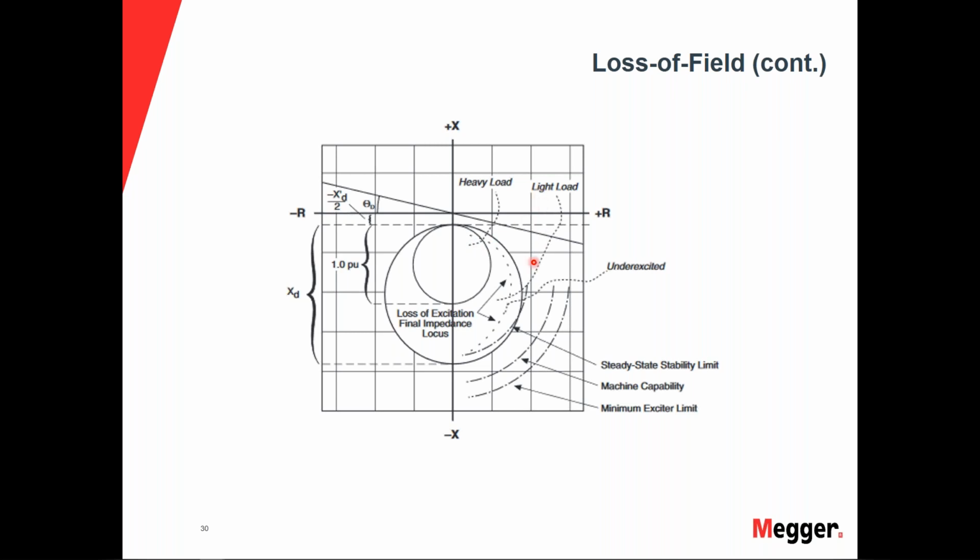In the lightly loaded case, if we're only using this for peaker generators or something that just has a light load as a supplemental to the system, then it gives you a little bit more time when it breaks into zone 2. It's actually going to give you a little bit more time before it gets into zone 1. Hopefully it doesn't, but generator protection has to take all precautions against protecting the equipment itself.